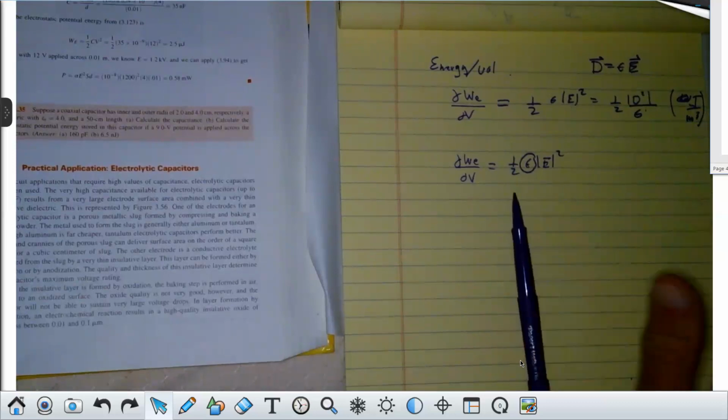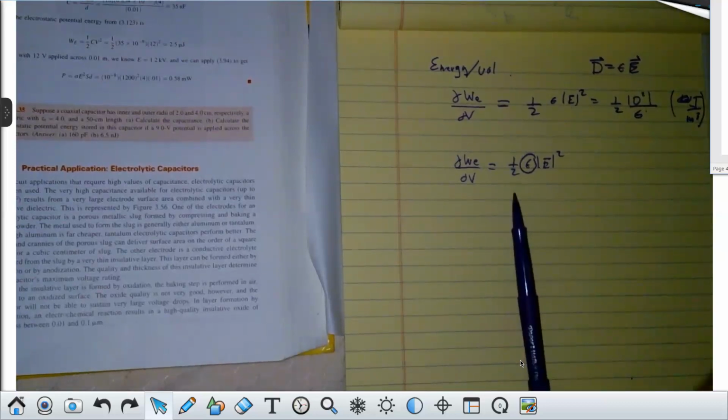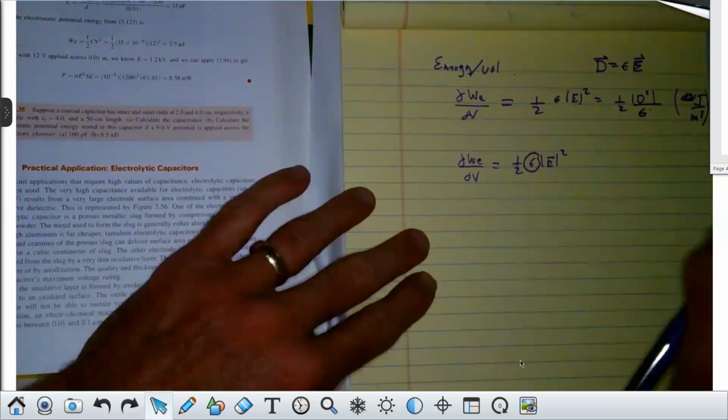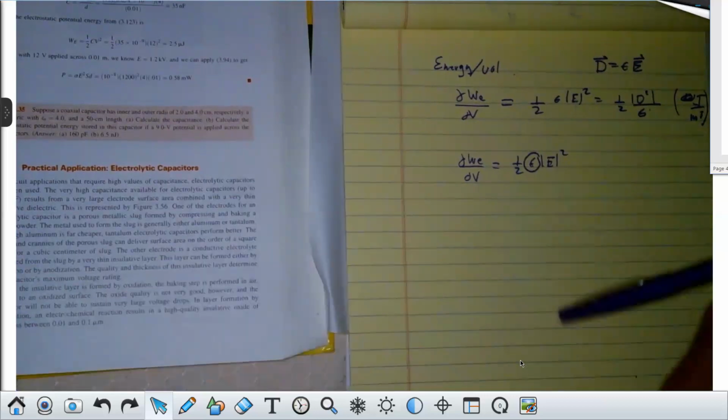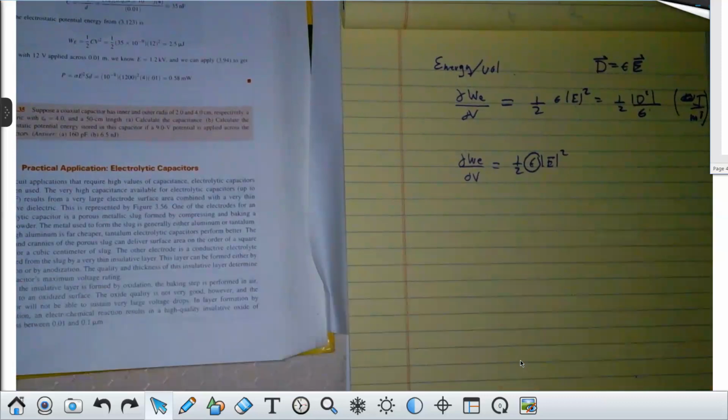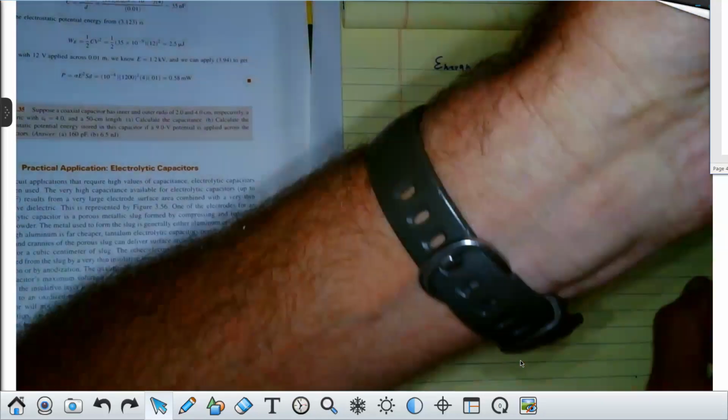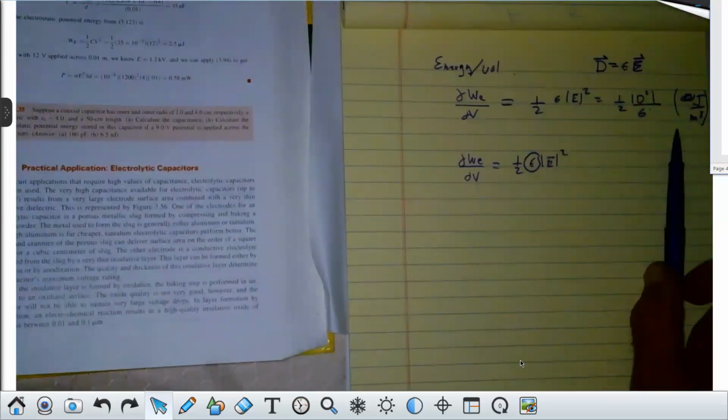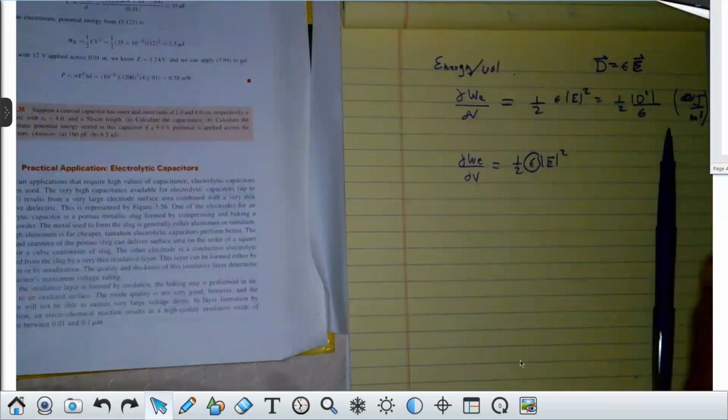But if you have a capacitor, you can get energy out very fast. The problem is with a capacitor, we can't store that much energy. Well, with supercapacitors, what they're looking for is they're creating epsilon relatives that are extremely high. So if you think about the capacitance, and we'll be doing this, the capacitance will be proportional to epsilon relative, and we'll see that in a second. But what they're trying to do is get epsilon relatives of maybe 100,000 to 1,000,000. That means a capacitor that normally would store maybe a microjoule would store a joule of energy. That's a large amount, by the way, a joule.